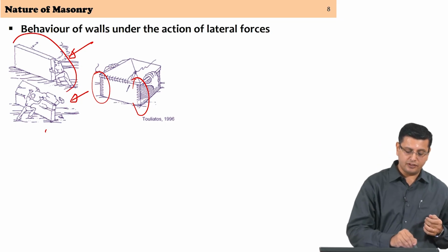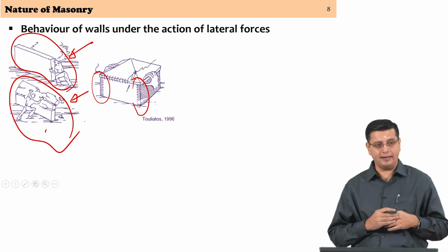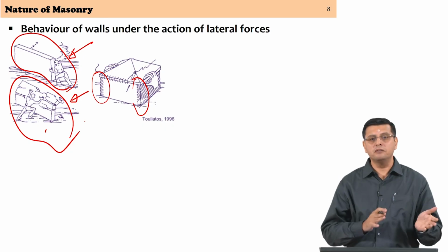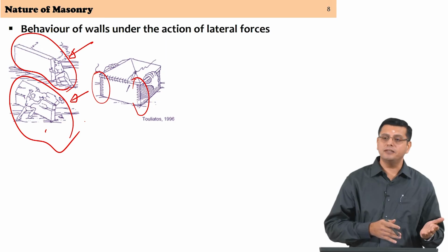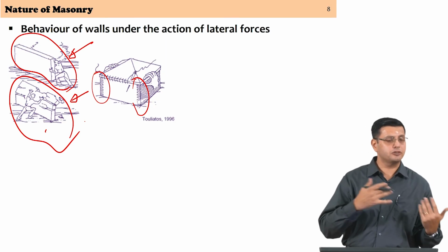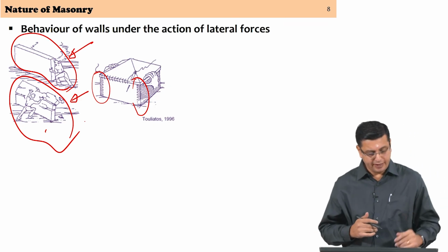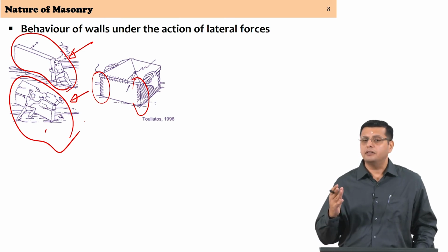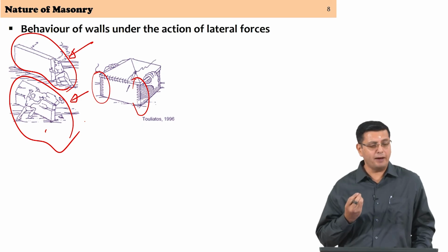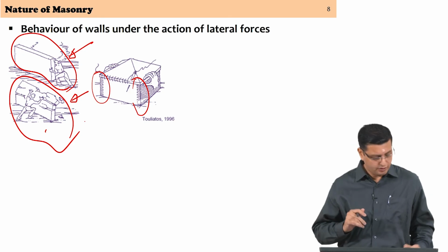So, this is referred to as in plane action, and that is referred to as the out of plane action, and we are basically examining a wall component with respect to in plane action and out of plane action. You will agree with me that both are looking at bending action in plane, bending action out of plane, right. It is subjected to shear, but there is bending in that direction, predominant direction in plane and out of plane. The second moment of area, or moment of inertia, is a good geometrical parameter that captures the bending strength, the bending resistance, right.